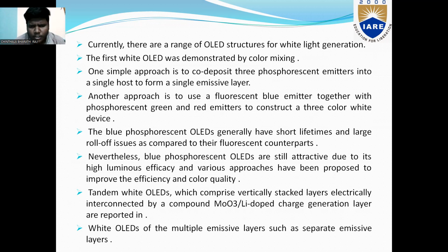Nevertheless, blue phosphorescent OLEDs are still attractive due to their high luminance efficiency, and various approaches have been proposed to improve the efficiency and color quality. Tandem white OLEDs, which comprise vertically stacked layers electrically interconnected by a charge generation layer, have been reported, as well as white OLEDs with multiple emission layers such as separate emission layers.